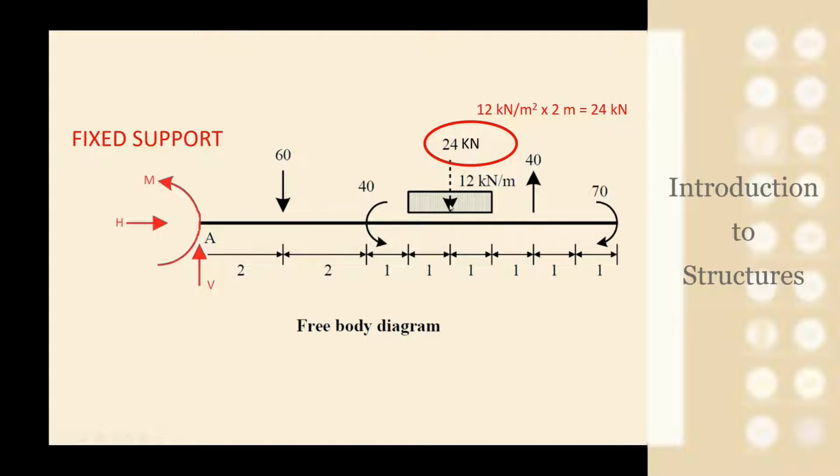We do that because it's simpler to write equations when you refer to punctual loads instead of the UDLs directly. When you have practice, you can do it directly without simplifying in this way. But for the moment, it's good practice for you, because you are starting to learn structures, that you replace this UDL with this punctual load for the calculation of reactions.